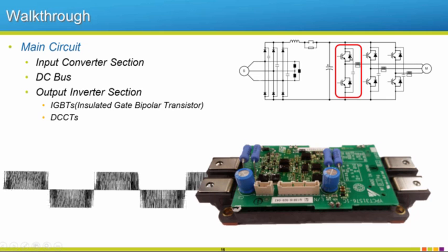Also this portion here. This is our freewheeling diode. So this allows our drive to take in regen. Whenever we decelerate a motor, we're actually running through these diodes and we're filling back up our capacitors. Once we fill up our capacitors, though, they have a certain limit. The problem with this drive is you can't go past this front end. So once that comes in through the diodes, it can't backtrack back out into our incoming line. So we're kind of stuck to fill up these capacitors. That's why people can trip out on things like overvoltage.